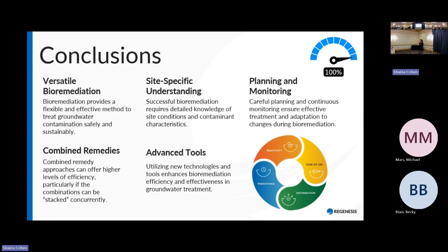Now, when we talk about chlorinated solvents, certainly not the case. They are definitely naturally occurring at lots of different sites, but often not at high enough levels, and often not to completely dechlorinate. We might have a lot of bacteria that can reduce TCE to cis and then stall out there.